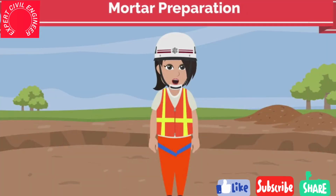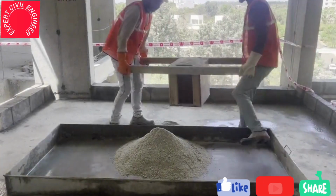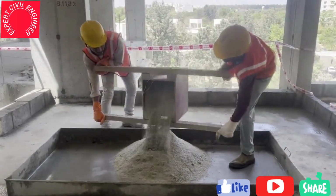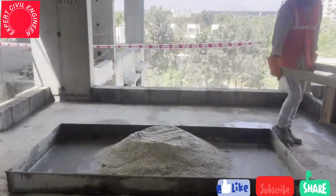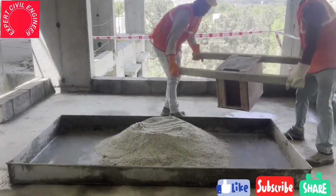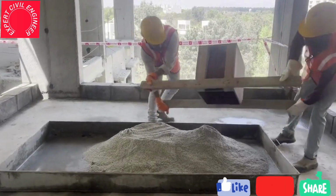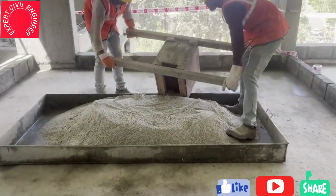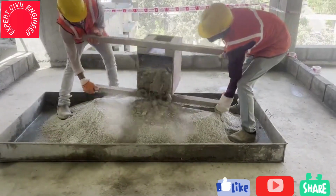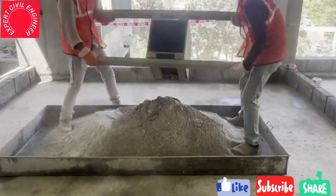Let us quickly understand the mortar preparation part. As shown in the video, 6 parts of fine aggregate needs to be added using measurement box. After getting 6 parts of fine aggregate, 1 part of cement to be laid using measurement box based on the mix specification.